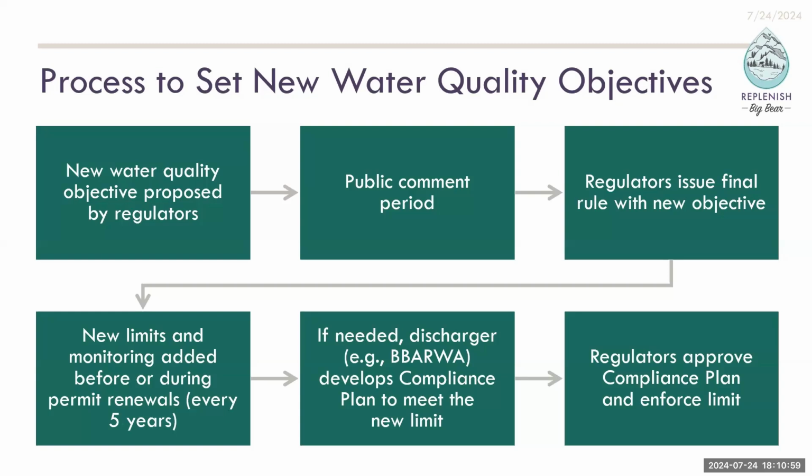The IDE performed. They got down to an 86% recovery rate on the RO system. The CCR, or the DuPont system, RO system just did a better job and got some of the constituents that we were looking at down further than the IDE process. But the IDE process worked. The DuPont system just worked better. And so that's part of the piloting: to test different pieces of equipment to find out what's the best equipment out there.